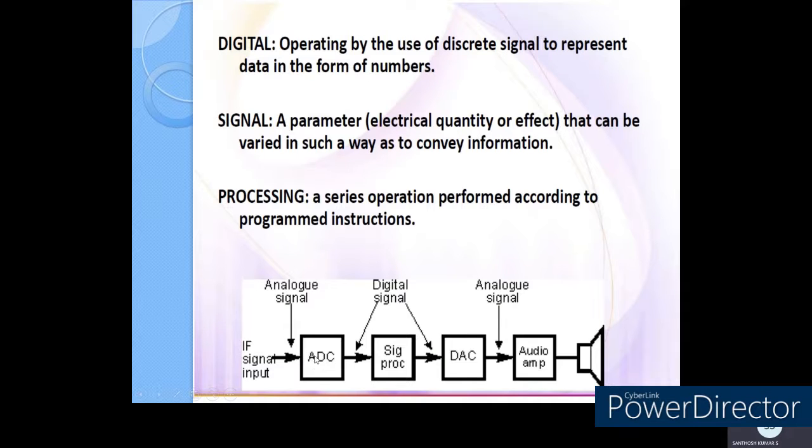So actually the sampling in the ADC is going to convert an analog continuous-time signal into a discrete-time signal. In terms of time, we are going to get discrete samples, and those samples will be given to the quantizer.